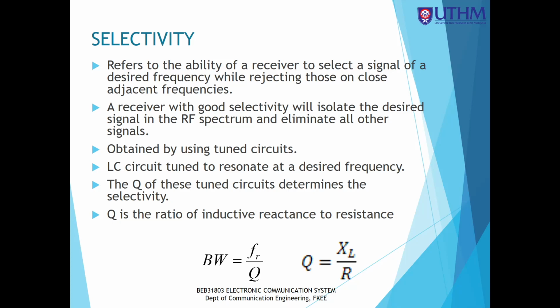So selectivity also has another parameter, what we call the Q factor, quality factor. Quality factor Q is equal to the inductive reactance divided by the resistance.